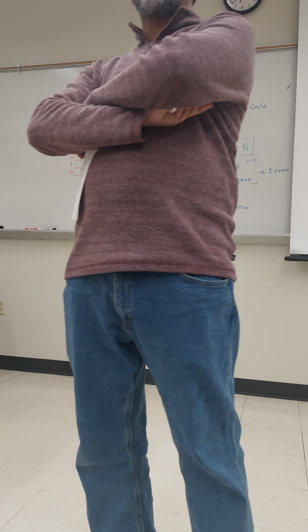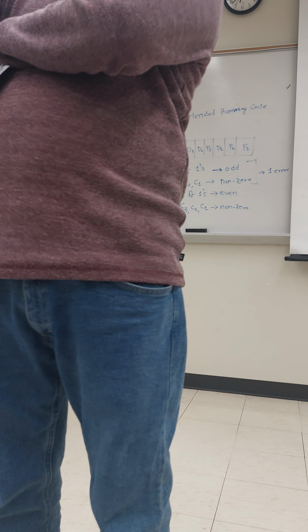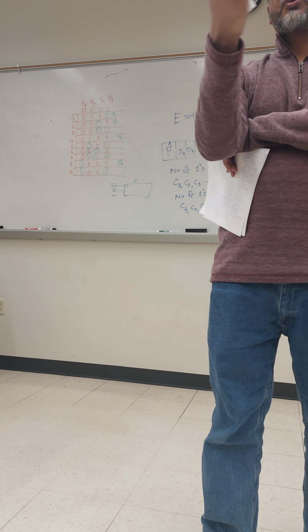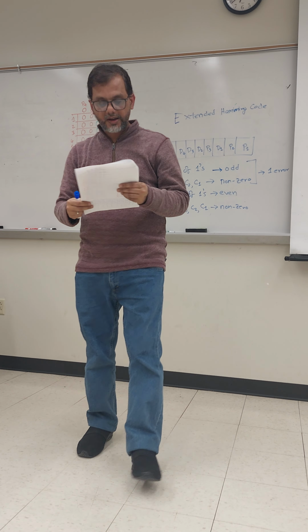Is it okay? No. We need to use the OR gate because it will generate high when any input is high. If you open any door, it will generate high. If you use the AND gate, output will be high when all the inputs are high. So we have 6 entrances. So if any one entrance is high, the alarm will not work. So the alarm will turn on only if all are high with the AND gate. By using the OR gate, we can.